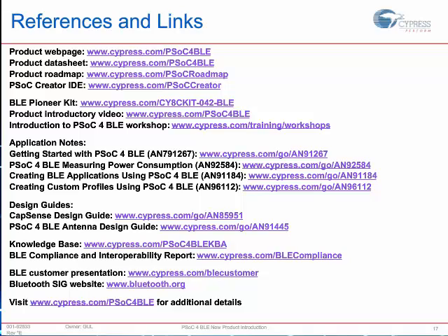It gives you that additional 128 KB of flash so you can store a separate image and use it for over-the-air firmware uploading. And Cypress provides all of the tools to do over-the-air firmware uploads in terms of projects, example projects, and even a mobile app, so I can do my firmware upgrades as easily from a cell phone.